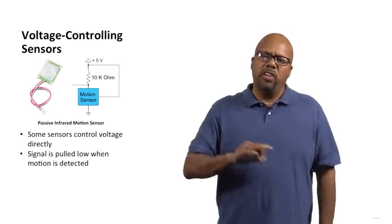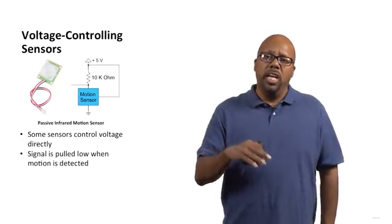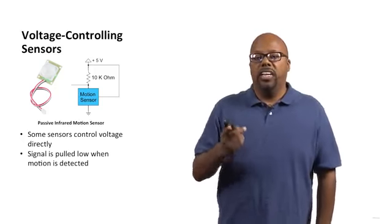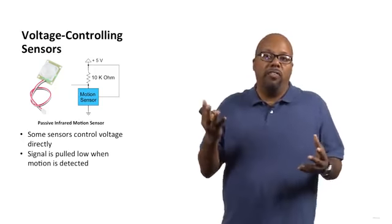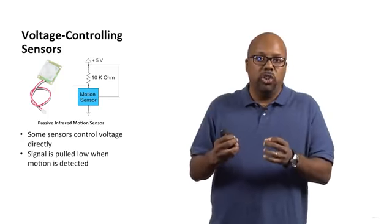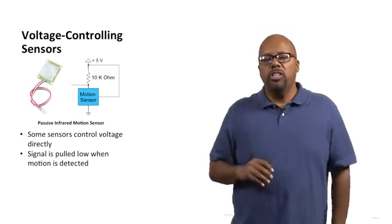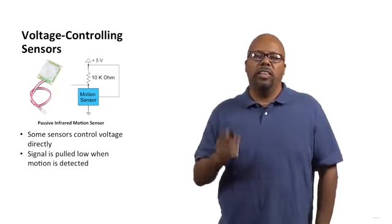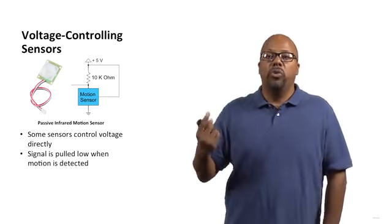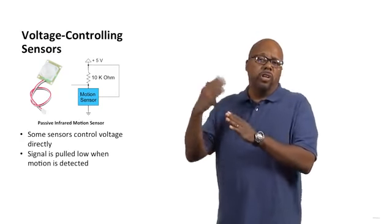So we want to make sure that if there's no motion, even though the motion sensor isn't assigning a value to this pin, this wire gets some value, right? And the value that it gets in this case should be a 1, a high voltage, right? Because the low is what happens when there's motion. So we want high to be associated with no motion. So when there's no motion, the motion sensor doesn't do anything, but that pin is connected to power, to +5, through the 10 kilo ohm resistor. So that's why we need that 10 kilo ohm resistor connecting it to power.